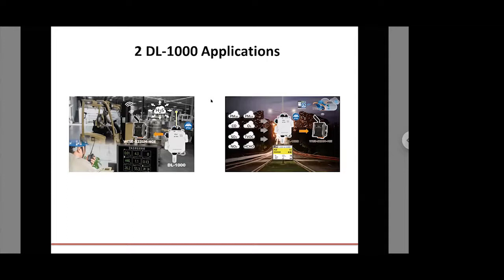The module is constantly taking particulate, CO, and CO2 readings at the street level. One of our WISE modules polls the module and sends the data back to a cloud-based SCADA system running our IoTstar platform, and you can use this to manage air quality messages on billboards on the street, or you can monitor air quality conditions in different zones throughout the city from a central control center.